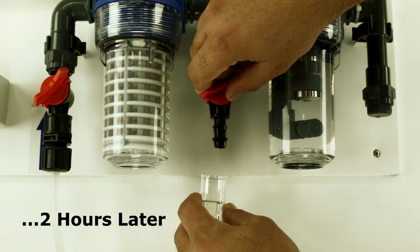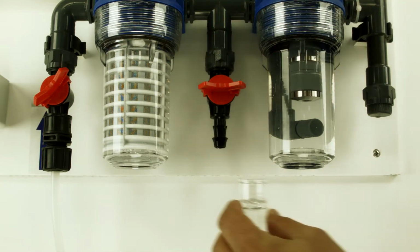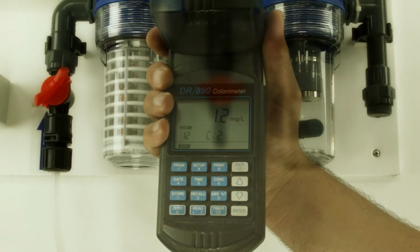2 hours later, take a sample of water in order to measure in your photometer and check the free chlorine level of the water.